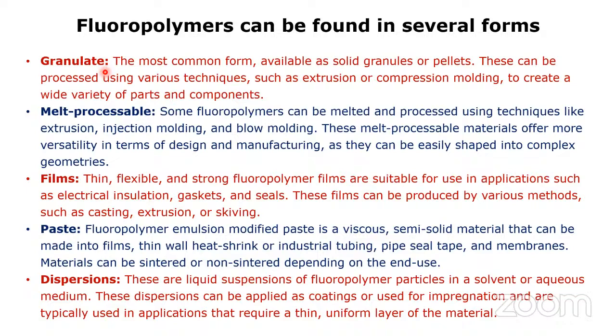The second form of fluoropolymers is melt processable. Some fluoropolymers can be melted and processed using techniques like extrusion, injection molding, and blow molding. These melt processable materials offer more versatility in terms of design and manufacturing.